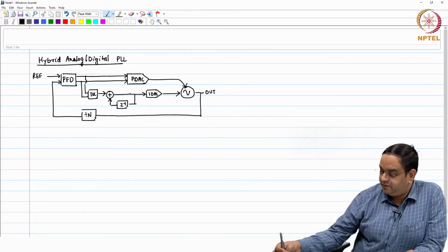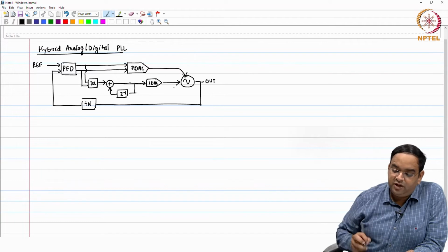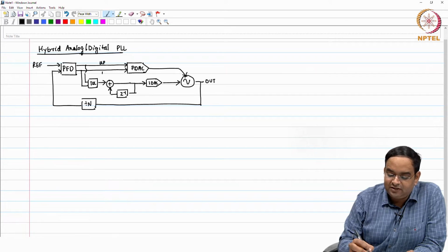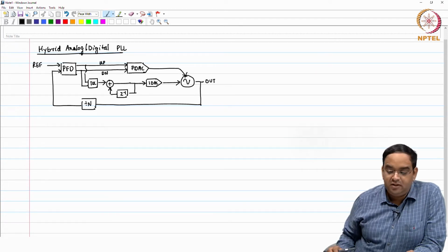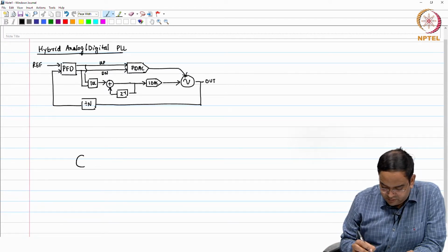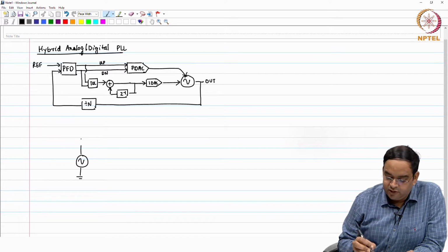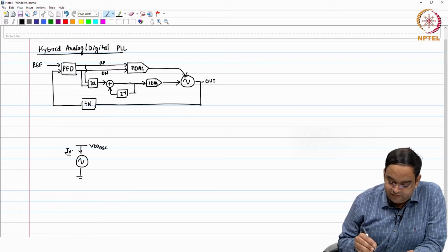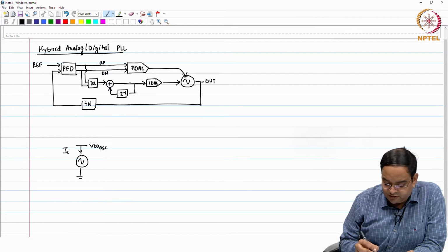Just think about how we are going to control the current controlled ring oscillator using our proportional DAC such that there is no quantization noise. While discussing the oscillator, the ring oscillator in our case, let us call this a VDD oscillator, and you have current flowing through the oscillator.